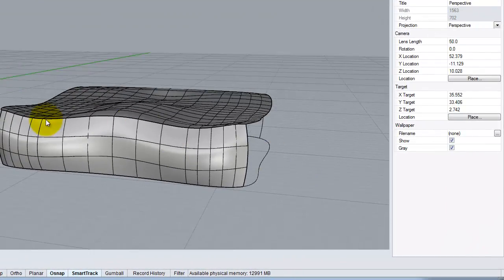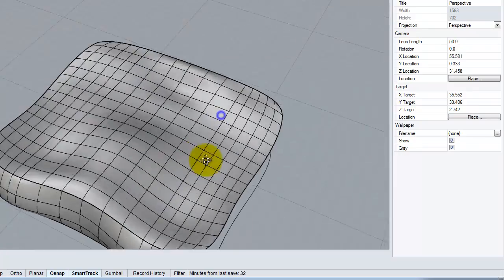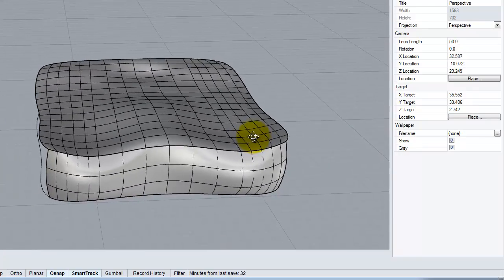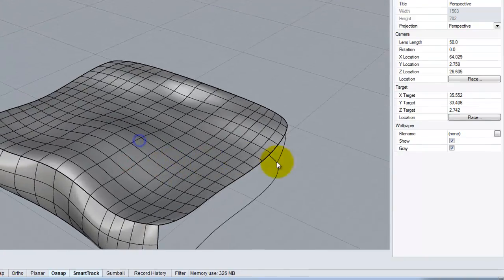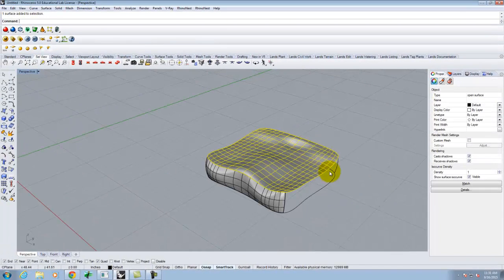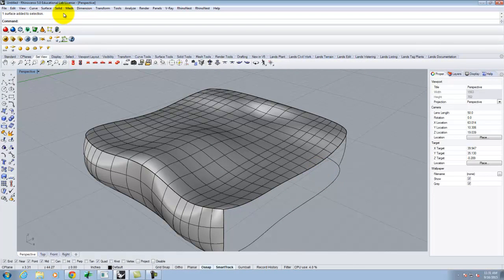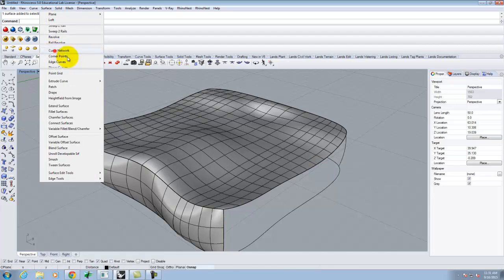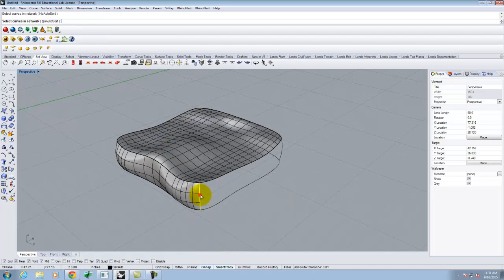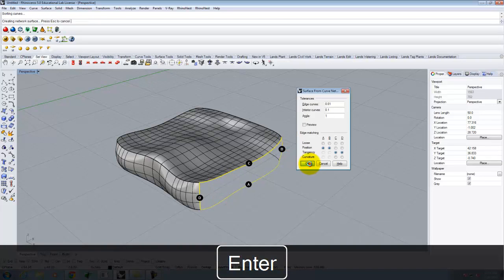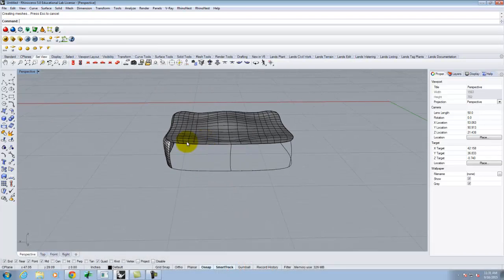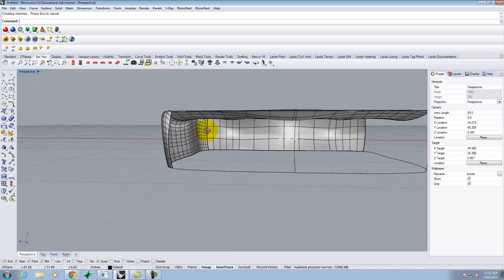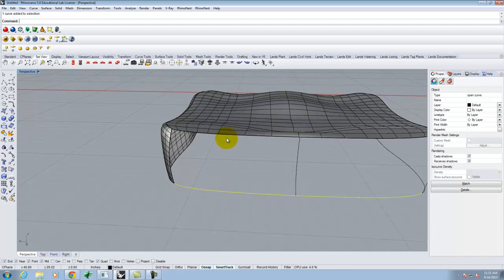And so you see, because I was thinking about what it would look like if it was kind of an older cushion when somebody kept sitting on it, I have the depressions of what I was intending. Okay? So on this side, I didn't actually create a special curve on the edge there. So we're just going to do a basic one. So I'll go to Surface, Curve Network. And I'll go ahead and say OK. All right, we'll do the same thing here.